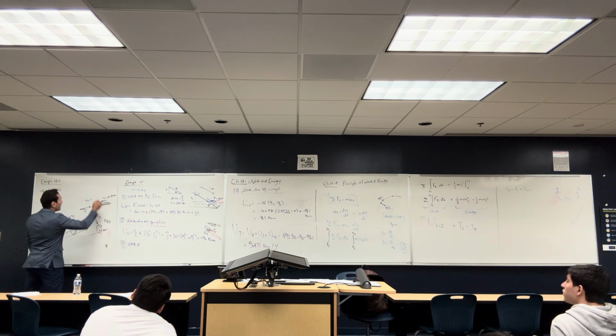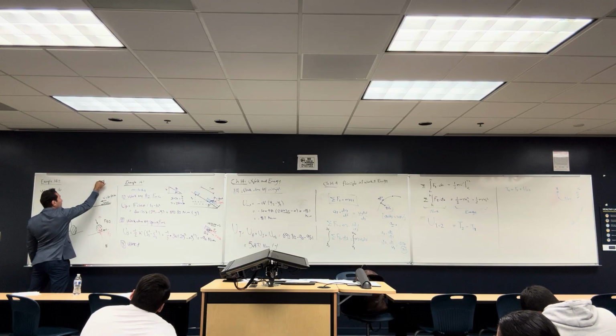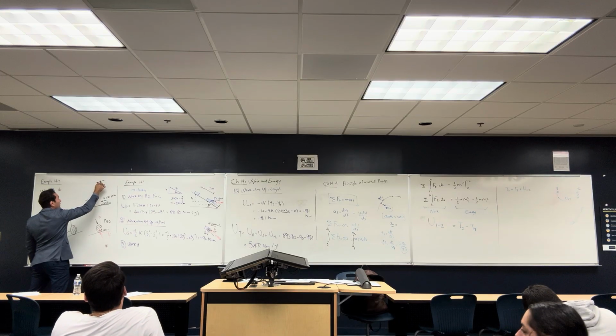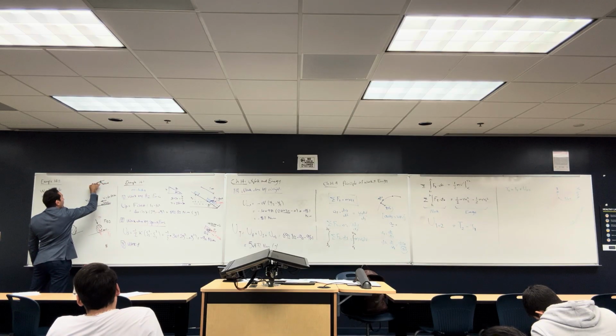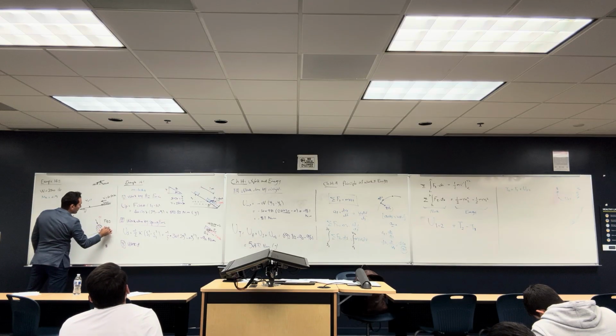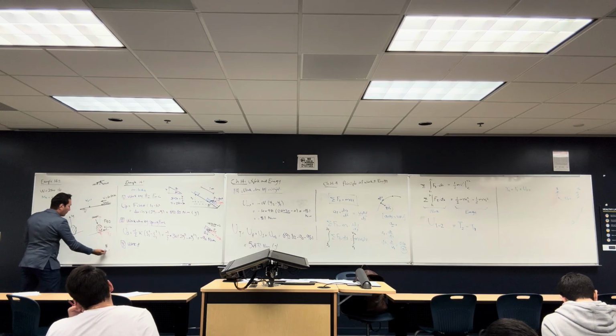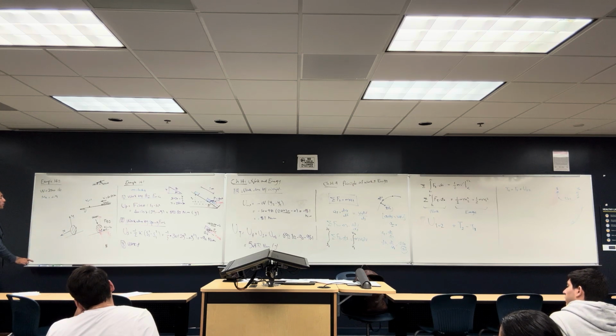And we did it a little bit ago, like we had something like here, we said that the weight is going down. I want to find the component that is going here, and the component that is going this way. We said that this angle is 10, so we have W cosine 10 and W sine 10. So this is W sine 10, and this is W cosine 10. The normal force is going in the y direction, the F of friction is in the negative x direction.